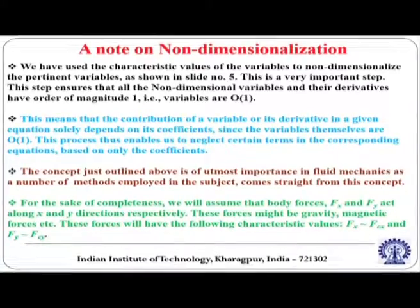Certain important notes for non-dimensionalization: we have used the characteristic values of the variables to non-dimensionalize the pertinent variables. This is a very important step. This ensures that all non-dimensional variables and their derivatives are of the order of 1.